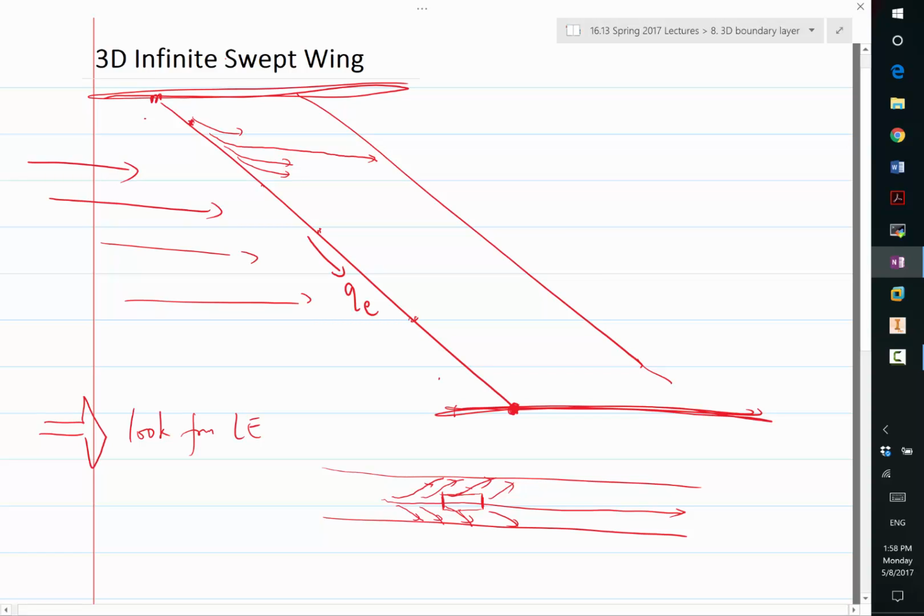so let's actually define the surface coordinates first. Let's define this coordinate to be x and this coordinate to be z. This is a case where you can have a global coordinate system that is not only orthogonal but also has unit normal. You can define a perfectly regular grid on this airfoil, and every grid cell is going to be square and of the same size. Okay. If you do that, first question is, how does the pressure vary in the z direction?